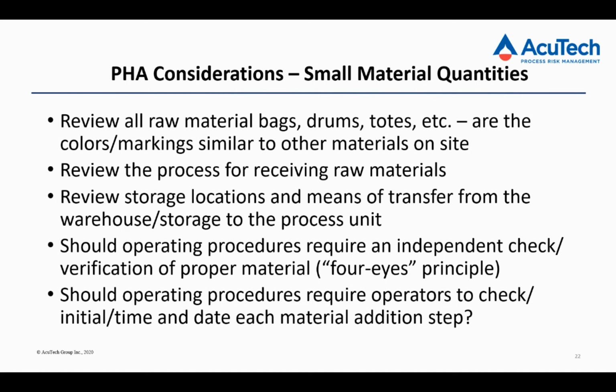Again, walk through the process all the way through, from the truck at the gate, getting those bags or drums or totes into your warehouse, and then following them along from the warehouse to your production to the reactor manway. Do you have sufficient verification steps? We sometimes call that the four eyes principle: the two eyes of the operator and the two eyes of the guy who's doing the check, the supervisor or another operator.